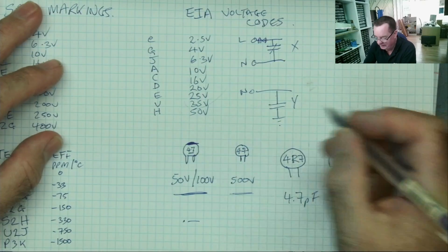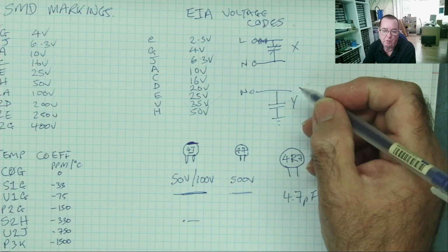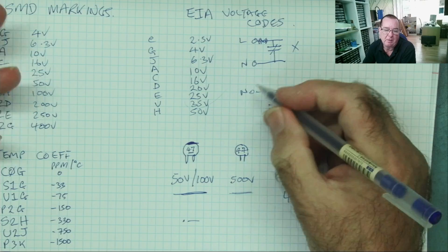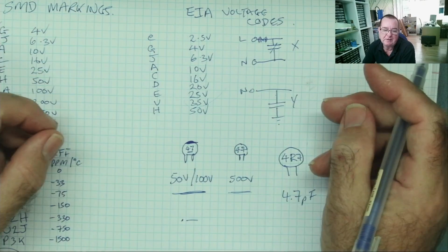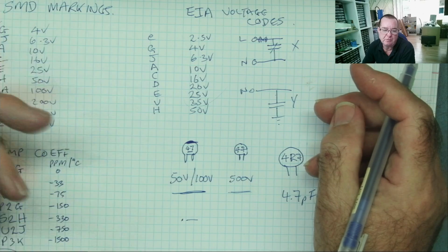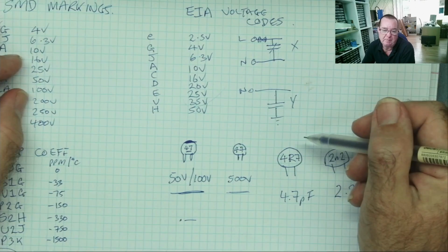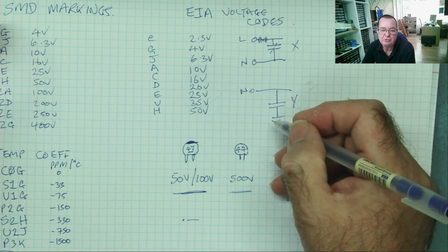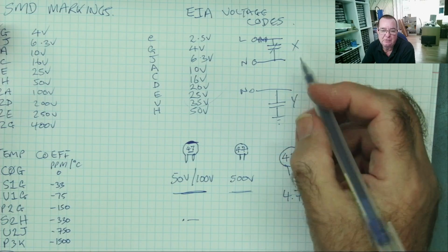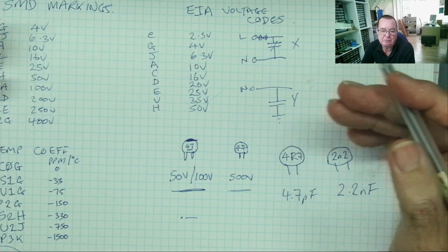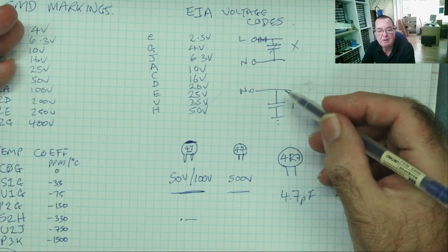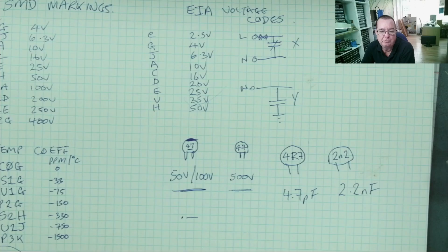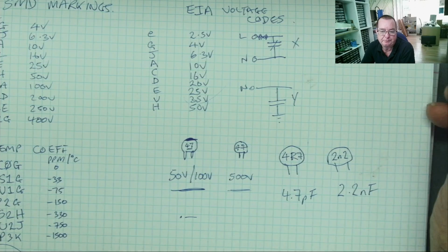The Y capacitor is connected from one of the mains to ground. Now, I say neutral, but with, for example, an EU plug, the plug will go into the main socket either way, so it may be live. If this was to fail and go short circuit in the same way, it would actually cause a risk of electric shock because you're now shorting either live or neutral to ground.